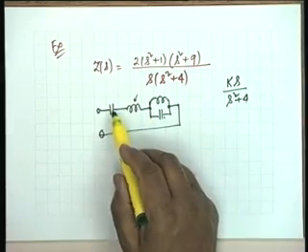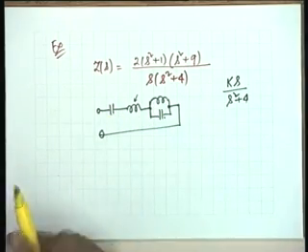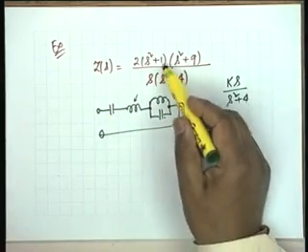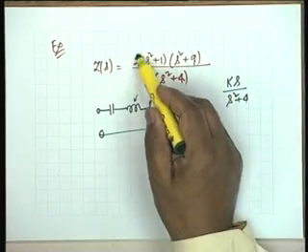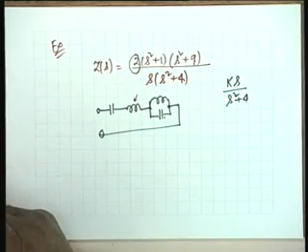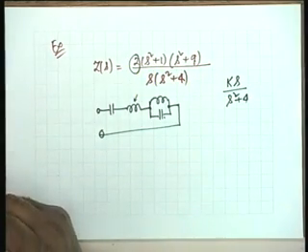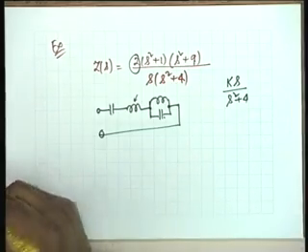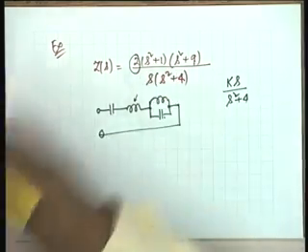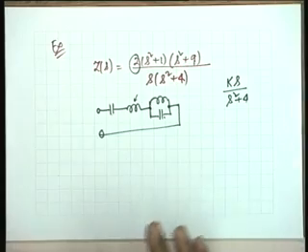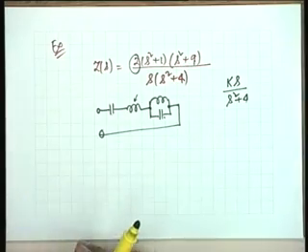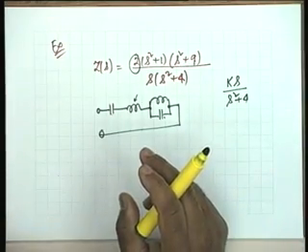The total number of elements is 1, 2, 3, 4. How many specs are there? 1, 2, 3. No, this is also a spec, the multiplying constant, and therefore there are 4. You see, if this multiplying constant was not there, element values would have been different. Okay, inductors would have been halved and capacitors would have been what? Doubled. Okay. So this is my Foster 1 form.